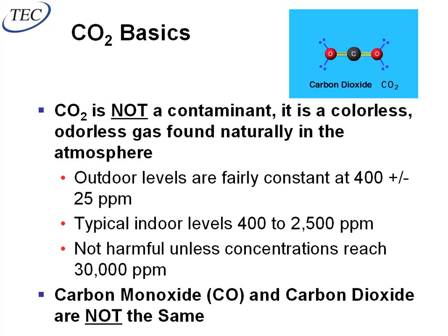For the most part, having high CO2 levels is not going to kill anybody unless you get to very, very, very extreme levels, around 35 to 40,000 parts per million. In that case, not because CO2 is harmful, it's just because you've displaced so much oxygen, there's nothing left to breathe. But small levels, even say 2,000 parts per million, that's going to be too high, but it doesn't mean it's too high because CO2 is harmful. It means it's too high because we don't have enough fresh air.